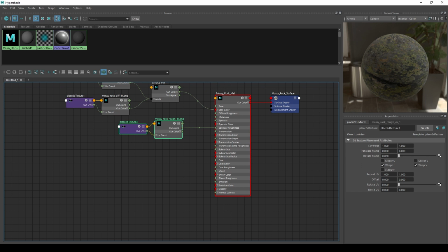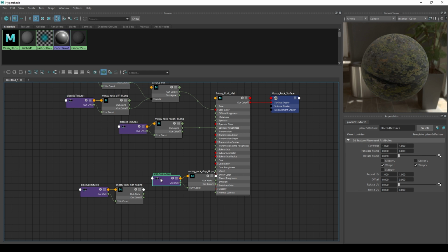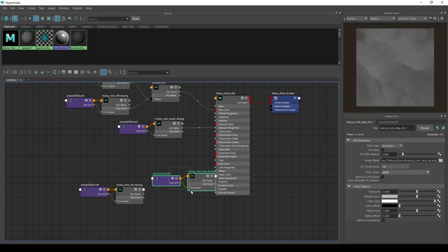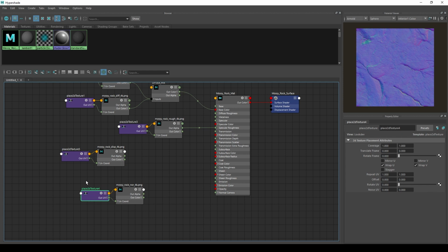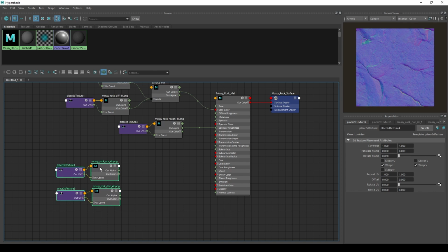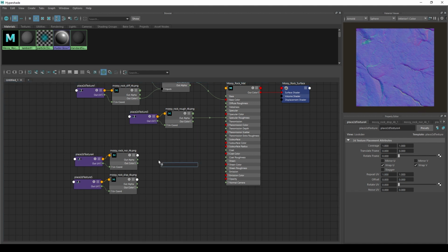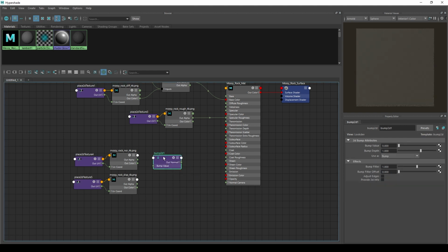Now I want to go in and add a little bit of cool textures, in the sense of adding a little bit of grit feel to our material. As you guys know, we use our displacement map in this procedure as well. You do not really need the displacement map for this. You can, and that's great. Now that we have our two surface distortion materials in here, so we can get some cool feelies and change in surface texture, we need to add our two bump maps as we do. So bump map 2D. This one we're going to rename to normal because it's for the normal map.